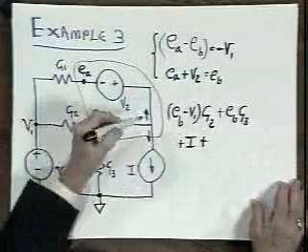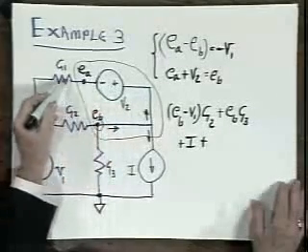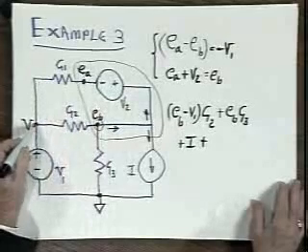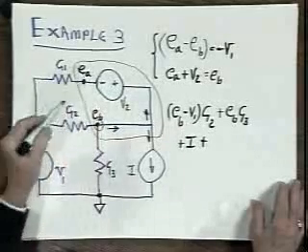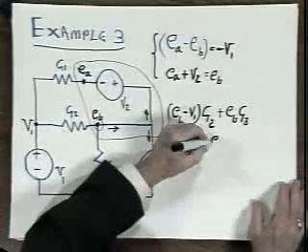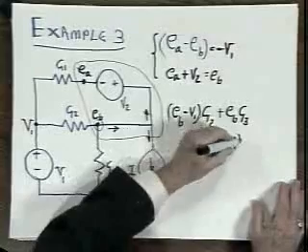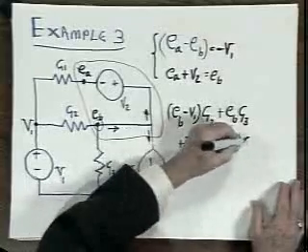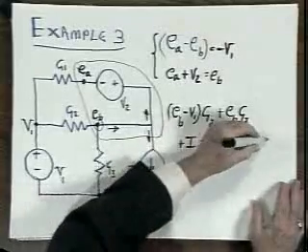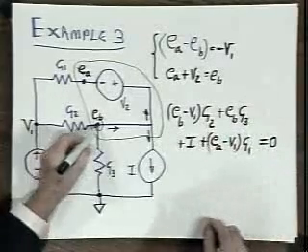And then I have to add the current here, which flows through voltage source V2 and through conductance G1 back to here. I can write that current in terms of E sub A and V1. It is E sub A minus V1 times G1. And these four terms must equal 0. That's Kirchhoff's current law at this node.